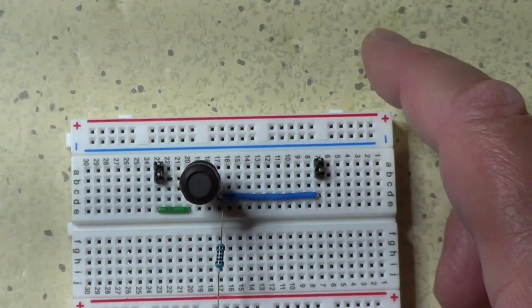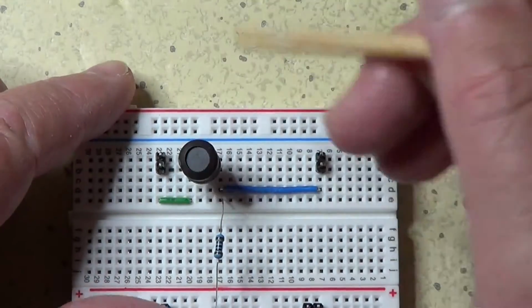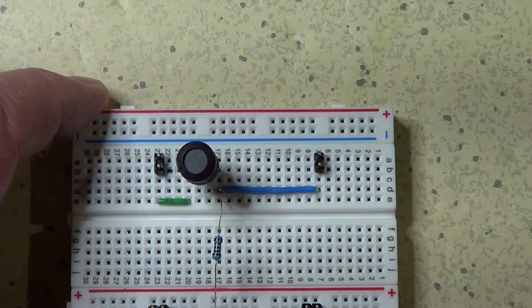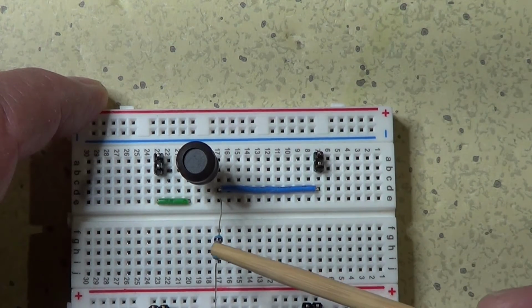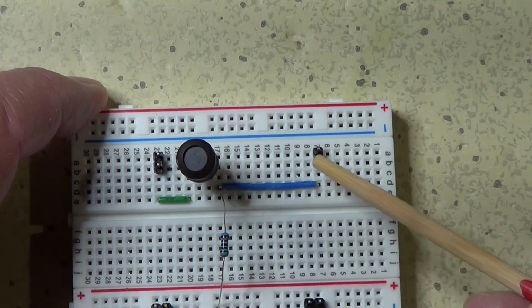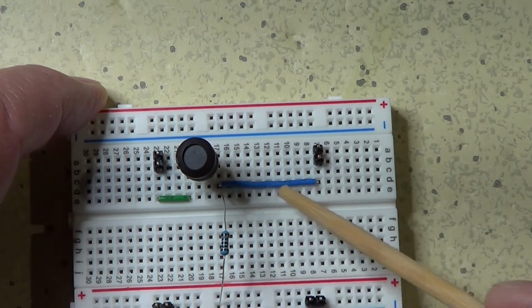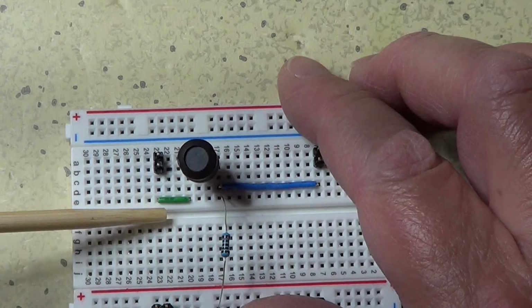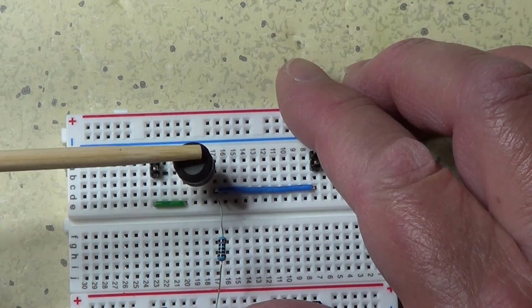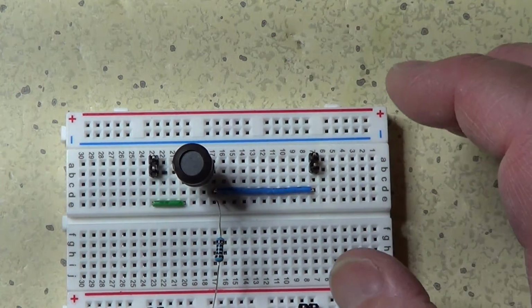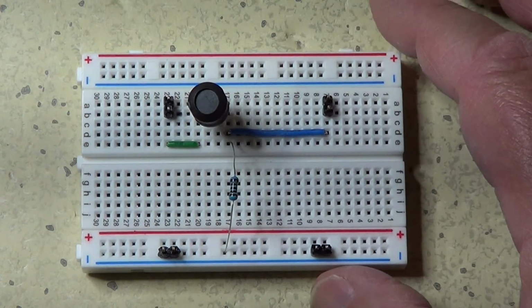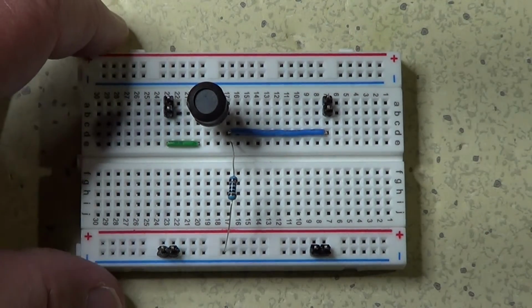I have connected the inductor in series between this point and this point. These 2 points are both on ground. This resistor is connected on this side, this blue connector and ground, and the green connector connects the inductor with the other end of the circuit. So basically this is the classical RL circuit in the low pass configuration.